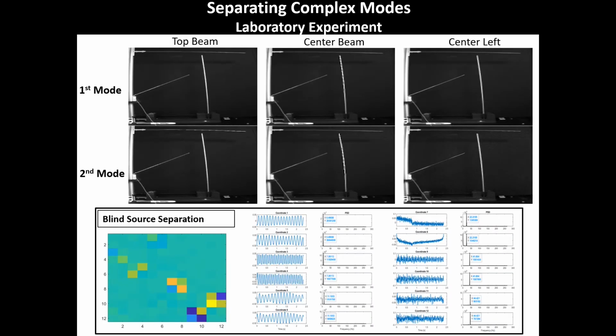After blind source separation, we were able to estimate two individual modes for each vibrating beam. In some cases, motion artifacts that are not structurally a vibrating beam are seen moving along with some specific beam, as is the case of the shadows in the background of the top beam and the wire tying the center beam, revealing subtle motions that otherwise could hardly be tied back to the motion of that specific beam.